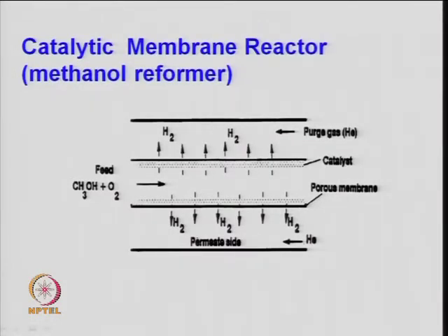So, one thing is thermodynamics, right. You know that when methane reforms, or any alcohol reforms or is partially oxidized, we get hydrogen, carbon monoxide, carbon dioxide, and maybe some other unwanted products also. So, there is some kind of equilibrium conversion during the process. Now, take a CO removal system, say for fuel cell application where pure hydrogen is required, because the electrodes generally used in the fuel cell are platinum or palladium type electrodes. So, a small concentration of carbon monoxide may poison the catalyst, right.